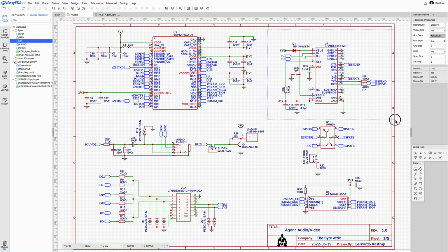Now this is the USB bridge. It would translate the USB signals that come from the USB port into serial signals, these two, that go to the ESP32. That's basically what it does. These are bypass capacitors. Now, the rest of what you see, you have to read the data sheet to really understand what these two capacitors and what this resistor are doing. These are the two lines that come from the USB jack, the USB port. They form a differential pair, D plus and D minus. They come in here, and then after the translation done by this chip, they become serial signals that go into the ESP32. Let me see here. Yeah, these two signals here are these two signals here.